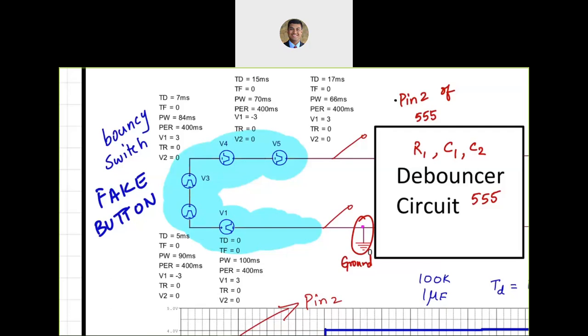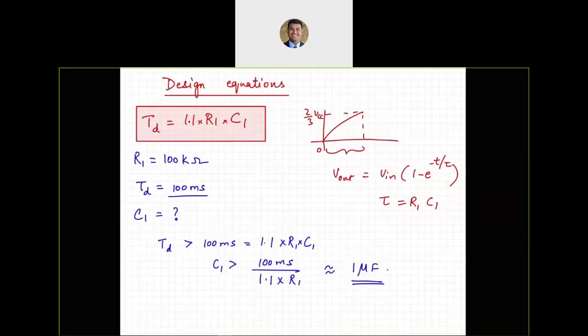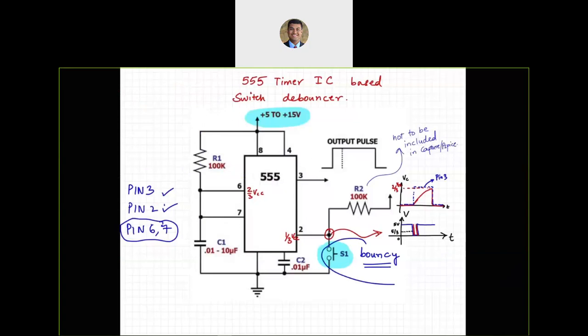So all of that needs to go into wherever you have your bouncy switch. So this is where your 5 V pulse voltage sources are going to go. That's how we are simulating a bouncy switch. Yes, ignore the pull up resistor. That's exactly right.